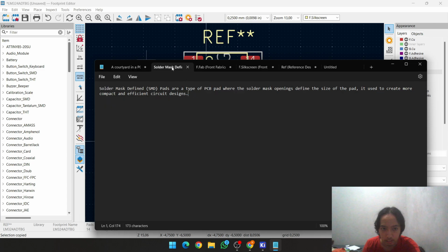Now, the SMD, that's this pad, also means solder mask defined. It is a type of PCB pad where the solder mask opening defines the size of the pad. It is used to create more compact and efficient circuit design.